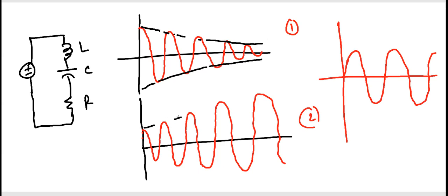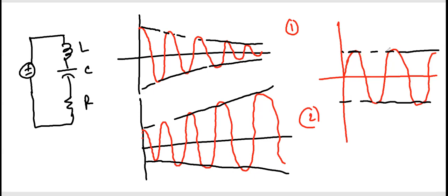And the second case, this is an unstable situation for the circuit, because at some moment it will burn because the voltage is increasing more and more. That will drag the current as well. So if I plot this as a current, the current is increasing in the second case, so it will burn anyway. And okay, this is critically stable. It can go in any way. It can go like this, or it can go like that, based on the damping factor, by changing the value of R, or a combination of RLC.